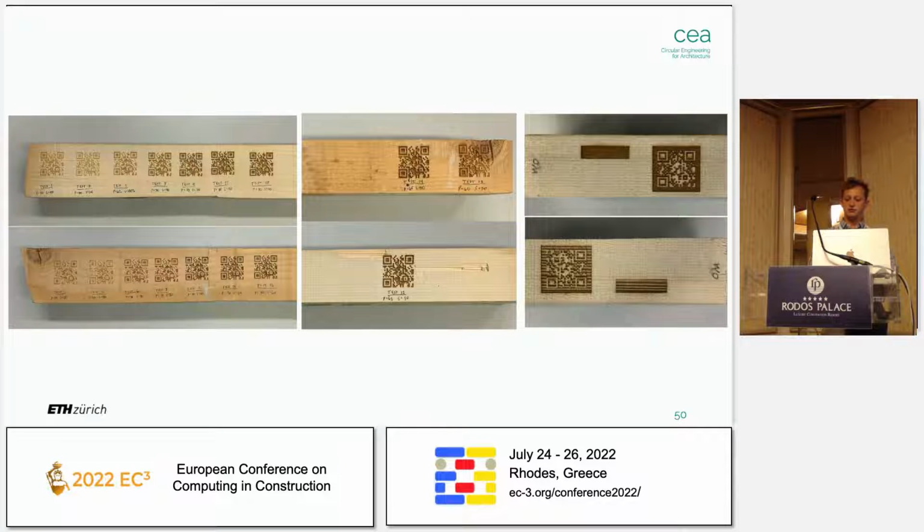On the far right, it was a unique idiosyncrasy of working with wood, where if you recall, wood is made up of several rings that expand outwards as the tree grows. So with that, in each ring, there's a harder part of the wood and a softer part of the wood. And if you use a consistent power of the laser engraver, you're going to dig deeper into the softer wood than the harder wood. So that kind of produced these striations on the bottom right there, especially if you have the light hitting the striations in a certain way. This prevented it from being readable.